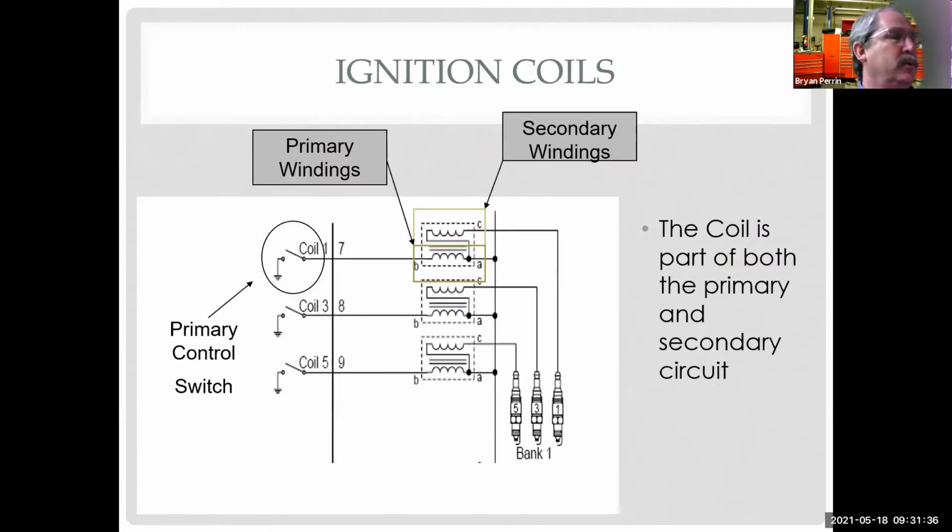So ignition coils, and we're going to get into exactly how ignition coils work. But even if I wasn't comfortable with this, I got a wire right here, which is my power wire. I can know it has to be because this is my ground and this is a load. So when we energize this, we flow current through the coil. When we release it is actually when the coil fires the spark plug. But again, the load of the circuit we're looking at is the primary side of the coil between A and B. And so we're turning it on, turning it off.